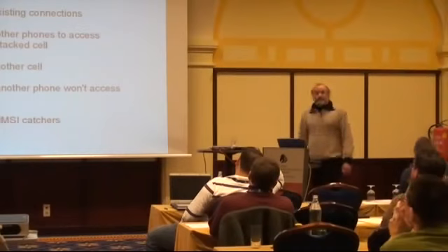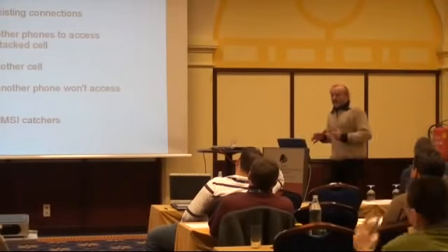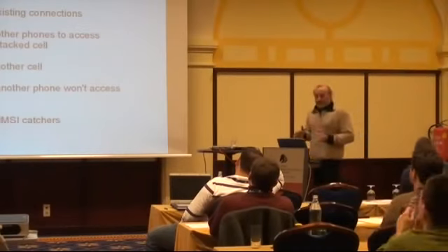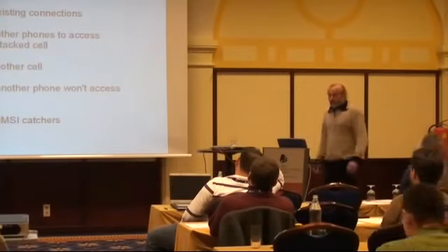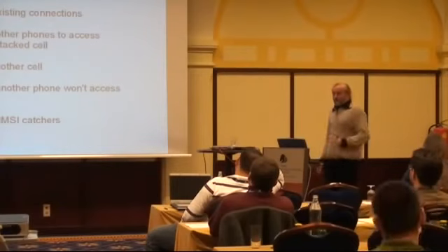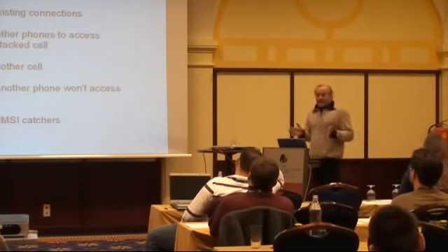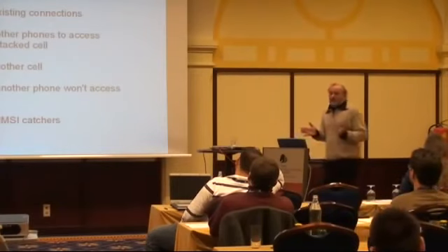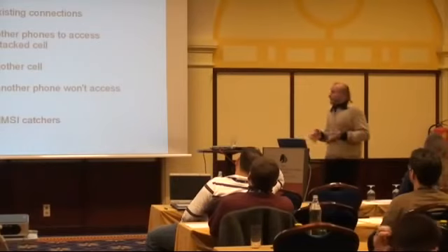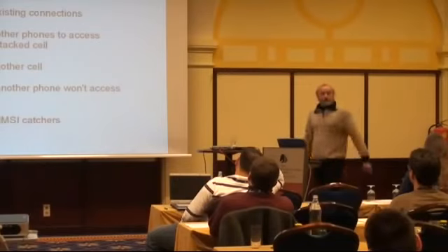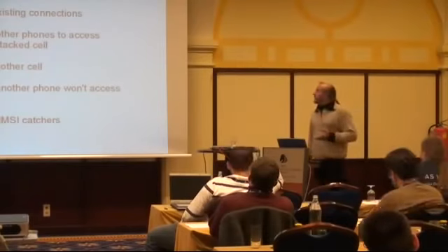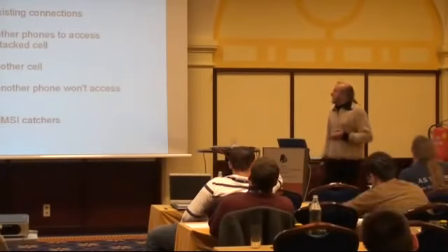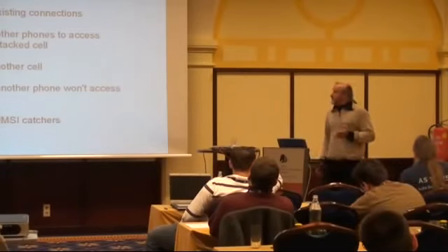One of the obvious things for a phone is that there is no encryption in use if an IMSI catcher wants to talk to a phone. So if the phone detects, okay, there seems to be an IMSI catcher in place and it wants to get me, a modified phone software could ask the user, do you want to deny the IMSI catcher and send continuous RACH bursts to it?